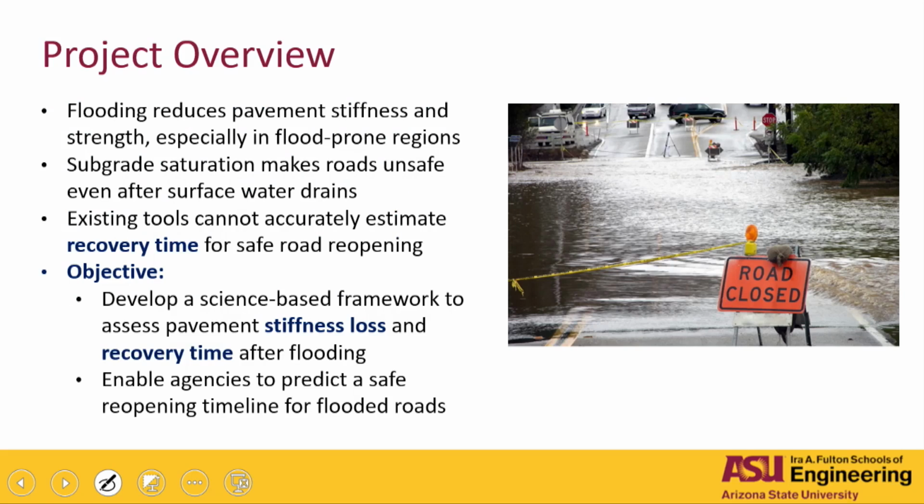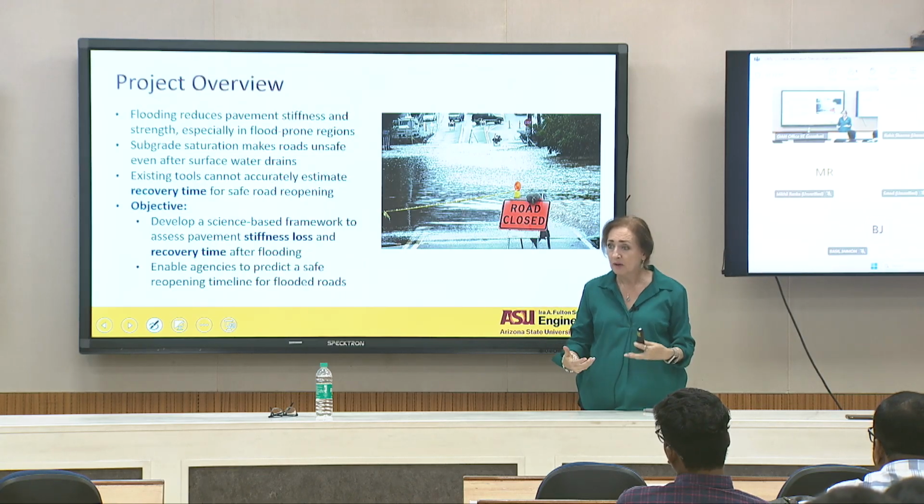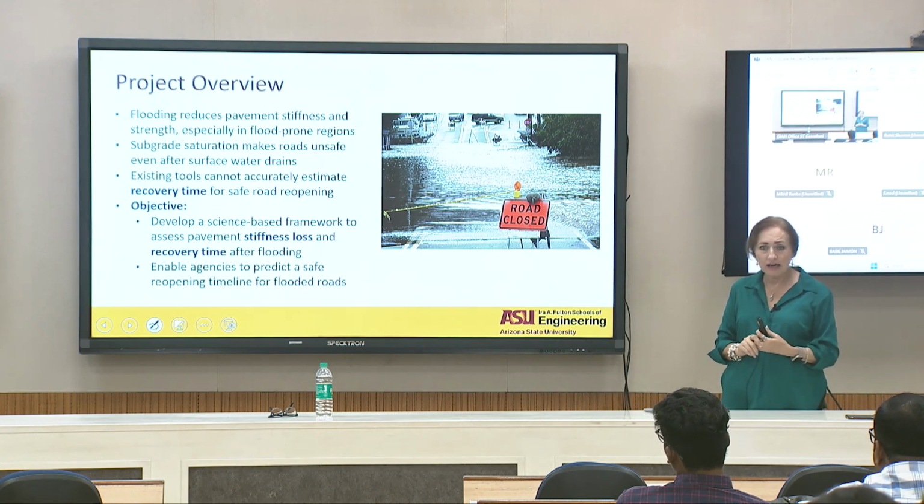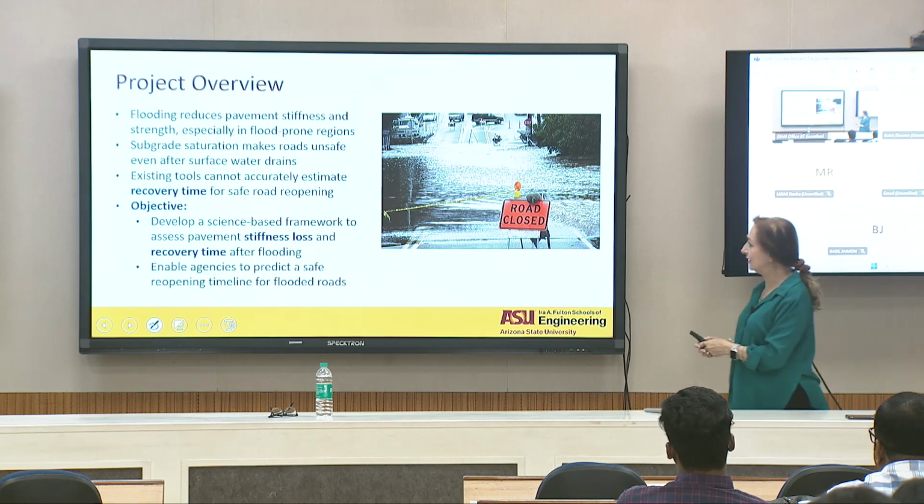So in the flooding, obviously, you got a lot of water in there and then the water starts infiltrating the soil. If everything is paved, the water will find a way into your soil, okay? Hopefully you're gonna have a good drainage. That's another point that we need to check, right? But the roads always have shoulders that are open to the environment, okay? So we get the water from the sides. We got cracks on the pavement, so we also get water through cracks, okay? There are many ways to get water into the subgrade of the materials, okay?